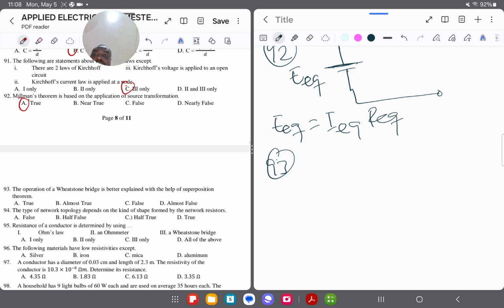Thevenin's theorem, because the place where you have the bridge, or you can call it the bridge resistor. In order for you to explain the Wheatstone bridge, what you tend to do is remove that load, or make sure that you place there a galvanometer, and with the galvanometer you adjust one of the resistors till you get a zero current, right?